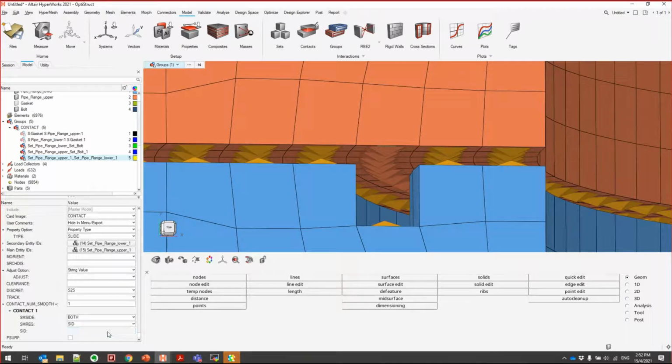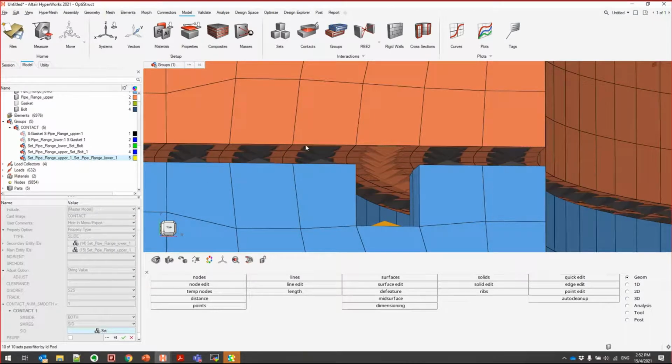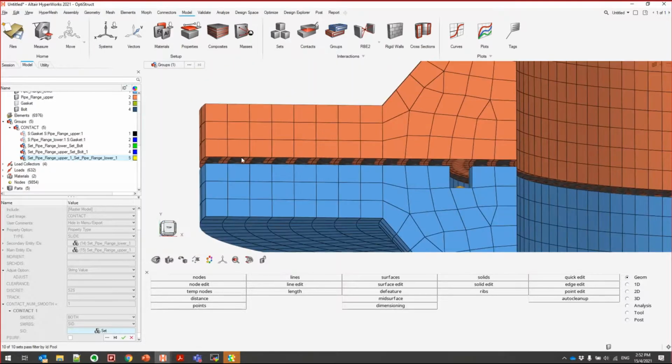In this case you need to define another set that says, maybe even for the front region, only at this area here I want to smooth. Otherwise, if you want to smooth the entire thing, just use all here. Right, so that's the smoothing that I missed out earlier.